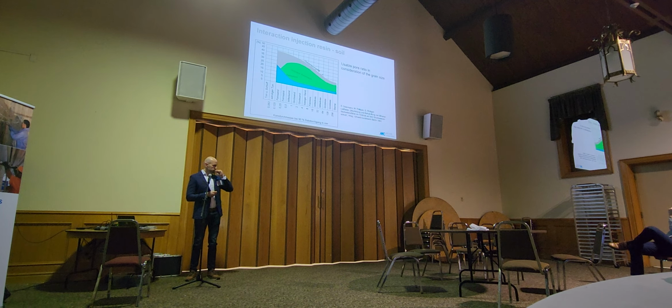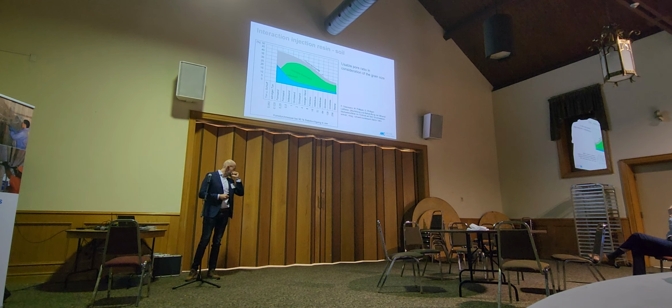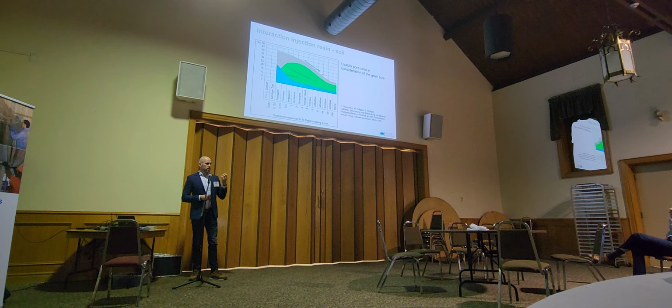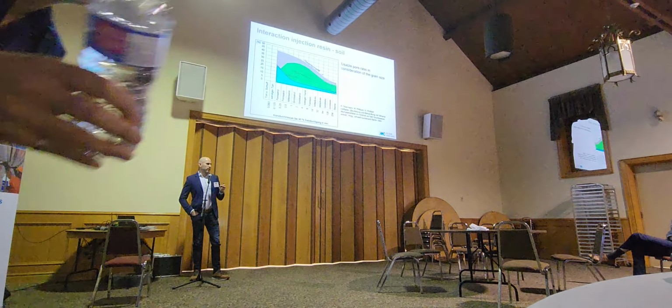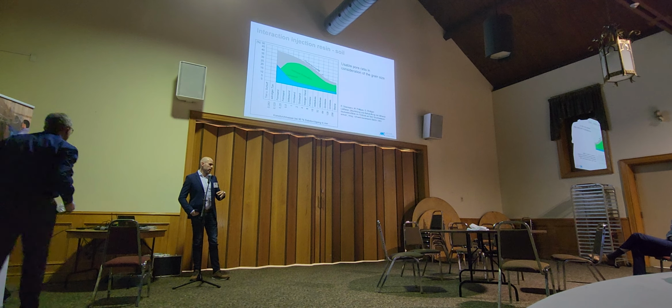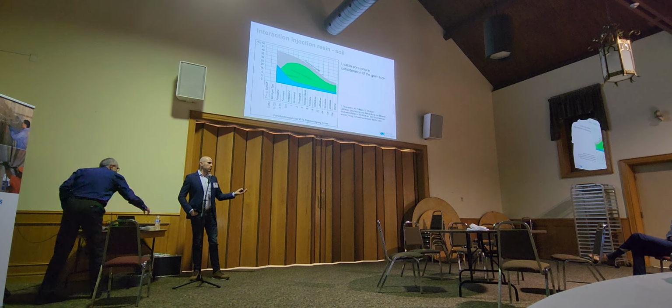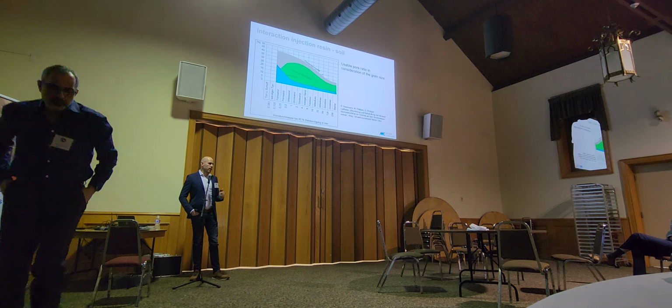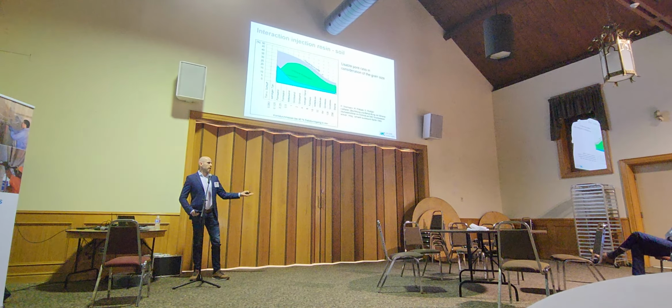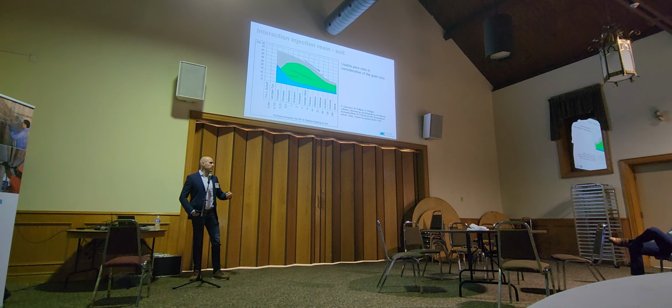We always have some porosity in the solids or in the granular itself, and therefore we usually calculate with 75 to 80% of filling degree. If you take 1 cubic meter of soil, you have 30% of porosity, so 300 liters, and 75 to 80% of that you can fill with your injection medium. Nothing more, nothing less.